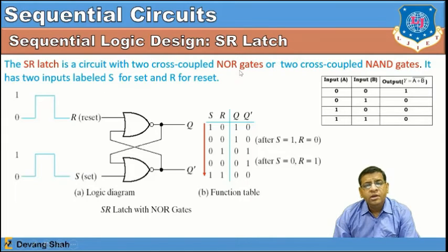So if you see the truth table or functional table of this SR latch, you can apply 0 or 1 to the reset and set pins. That's why it is called the RS latch, where as such these are NOR gates. So first consider, let's say, Q is equal to 1 at the initial condition. If Q is equal to 1, one of the inputs of the second NOR gate is 1, and set, you can check the set, let's say it's 0, right?